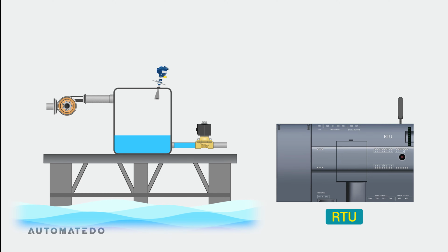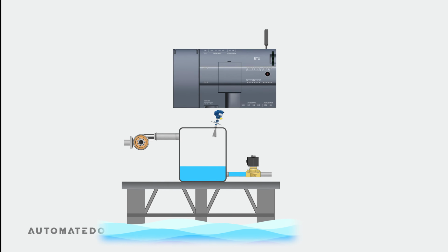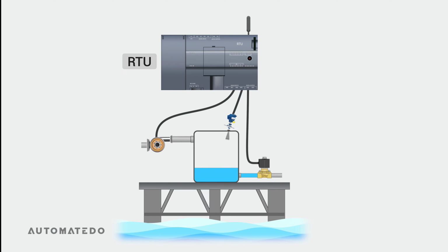An RTU is a rugged standalone microprocessor-based electronic control device deployed in an industrial environment at specific locations, which informs plant operators about what's going on out there all the time. It is intelligent and complex enough to automate a process with field equipment without needing input from a master controller. The gear that makes up the backbone of your industrial network will often report issues immediately when measured values fall below or exceed a predefined threshold.